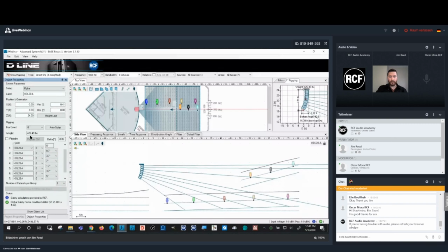And we could even, if we want to, manually shift the fly bar up to maybe target the top seats a little bit more by clicking the pinpoint. We can manually change the pinpoint, which is the pick point position for the fly bar. I'm going to pull it back 1 position, and we can now watch the array tilt back up a little bit.